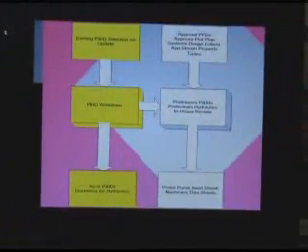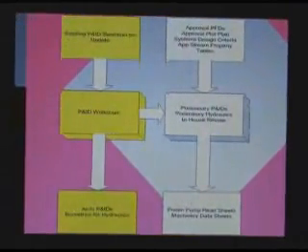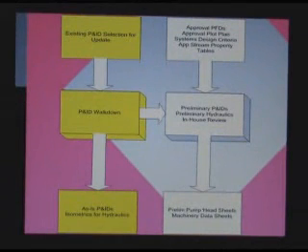And then the process engineers will produce the next issue, which is preliminary P&IDs, which they'll do some hydraulics, produce preliminary pump head sheets, and preliminary machinery data sheets. Remember, that's the first cut. It's not quite clear whether they are going to be firm. So it's always called preliminary.